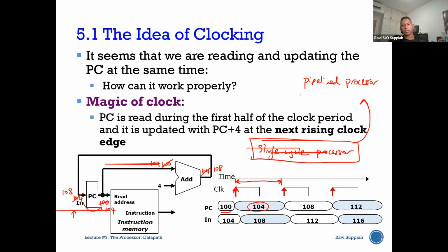But the pipeline processor basically allows us to break up the whole processor into small chunks, and just focus on executing that one small chunk within the clock. So the advantage is you can clock it at a much higher rate. Whereas in a single cycle, you need to make sure that the frequency is low enough to give it sufficient time to finish everything.